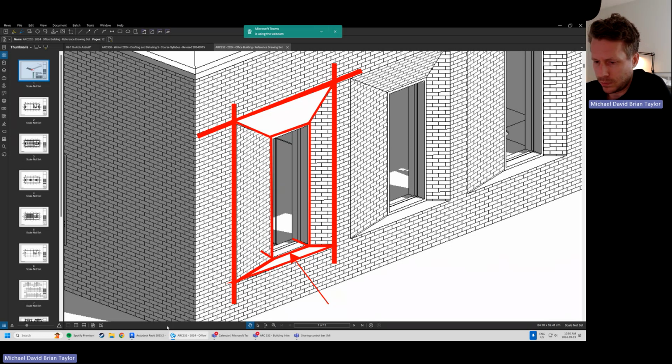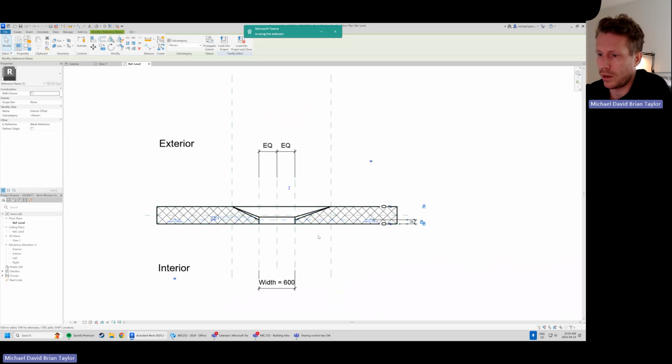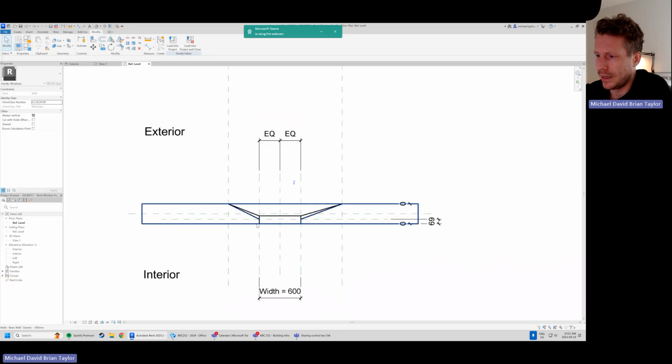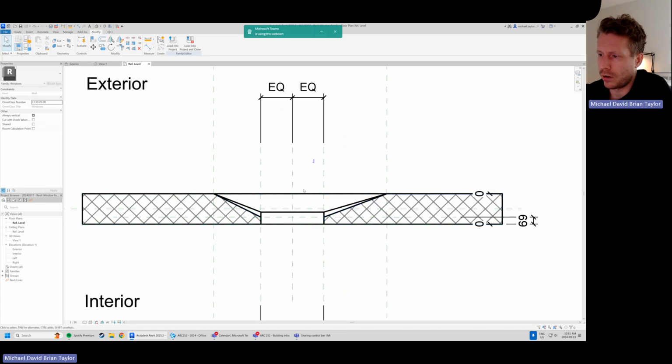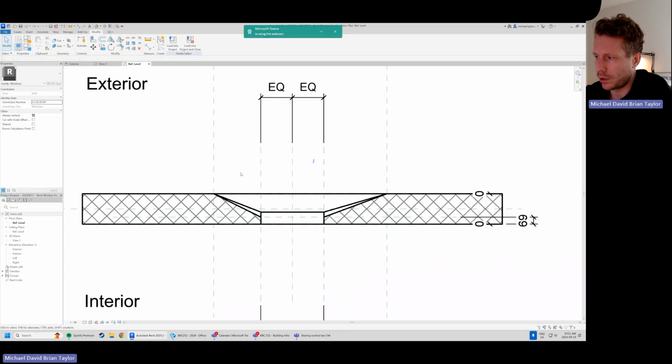Let's check it out. If I just jump into Revit here, I'm going to start with our window in plan. So this is where we left off. Remember how our reference planes are set. We've got this interior reference plane that's set. And just before I go too far here, you remember we've got these symbolic lines in here. So these are the symbolic lines. If I just click on one of them, it just says lines, windows. These will show up in our plan views.